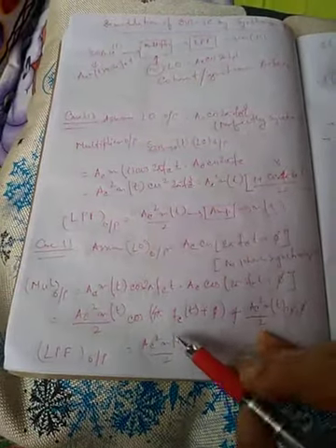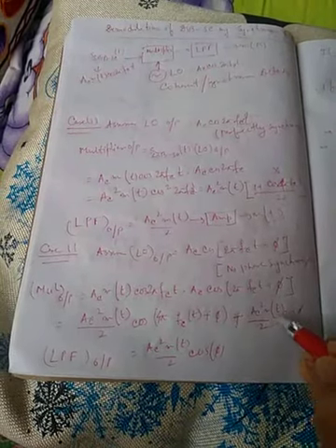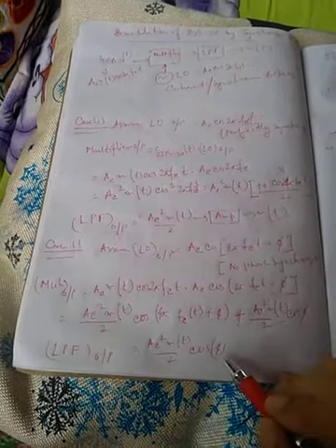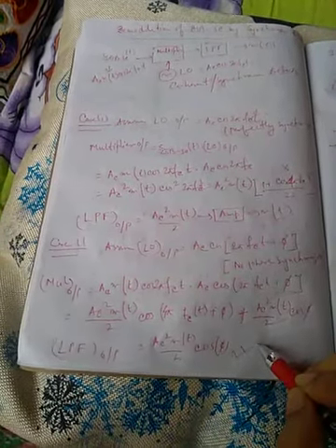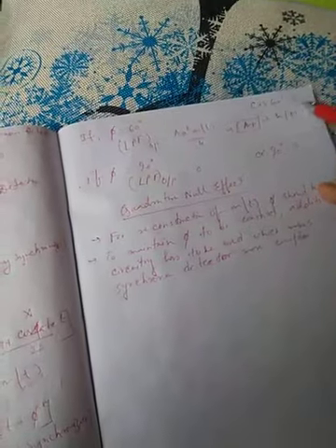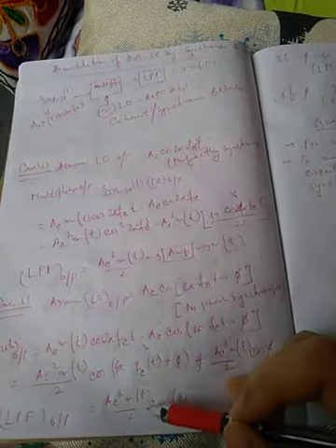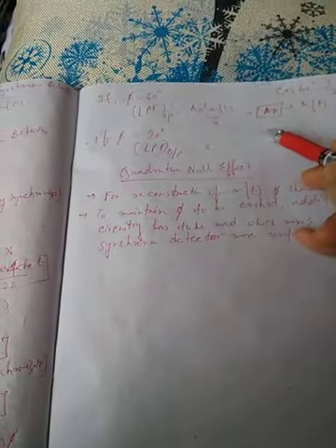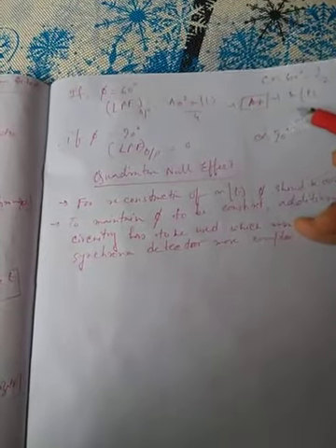So finally we are getting this output from the low pass filter, as this contains my low frequency message signal. So this will be passed through my low pass filter, and the high frequency term will get rejected. Now if phi equals 60 degrees, cos 60 equals half. So this message signal will become Ac square m(t) by 2 into half, so Ac square m(t) by 4. There is no problem, it will get passed through the amplifier circuit and it will generate my message signal.